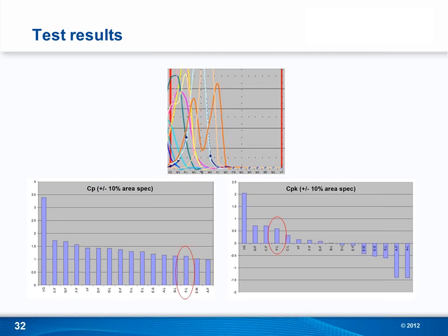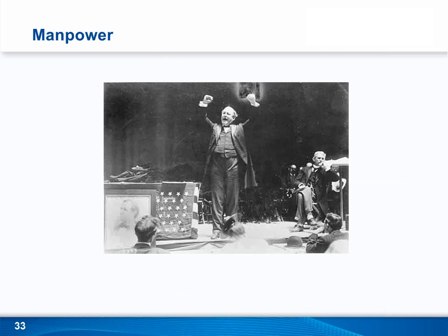With the higher cutting speed, you may also have to choose a little bit more power, and that little power may also increase the effective beam diameter of the laser beam. And that would, of course, result in a different aperture size, or at least a percentage aperture size. And that would explain the two humps. So all in all, it's a pretty clever move by the operator to try to save some time.